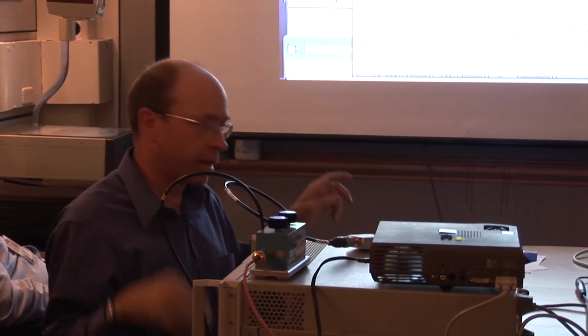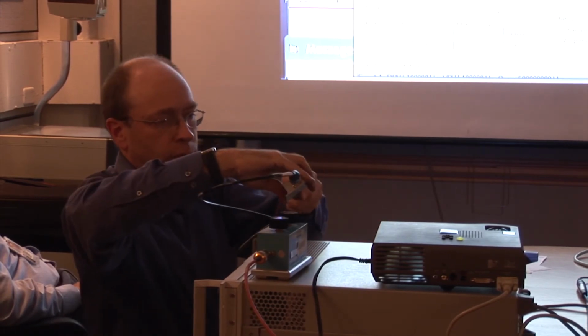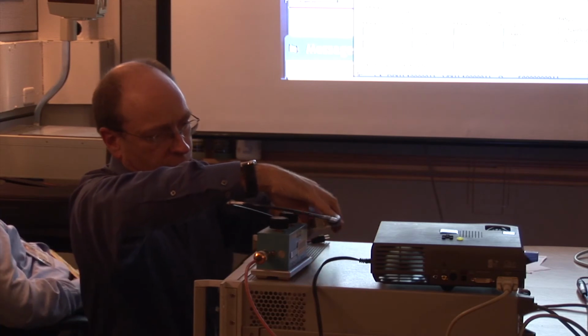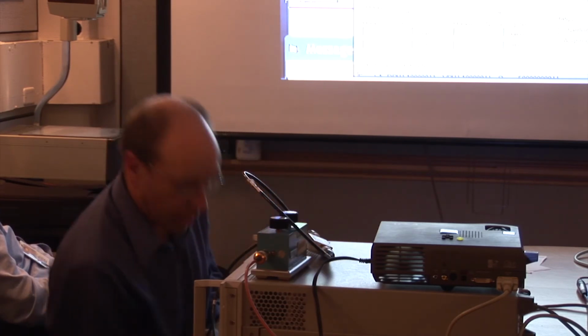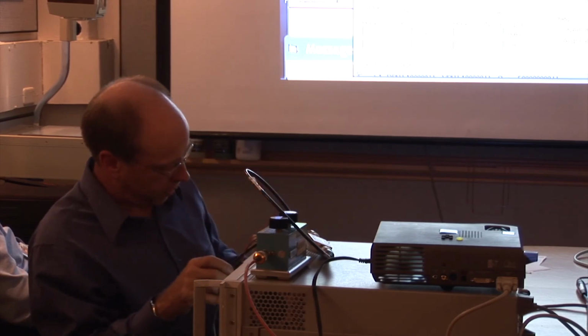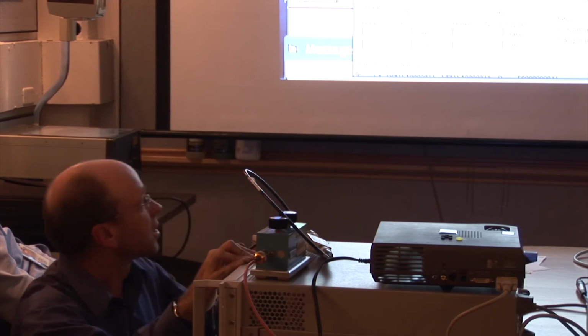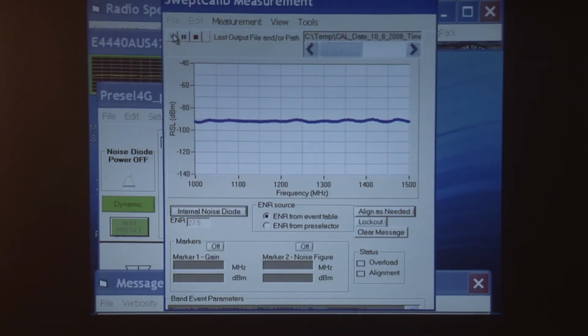Okay, turn on the preamplifier, 15 volts, like so. Okay, now, sorry for the delay there momentarily, but we've now put in an auxiliary preamp, electrically speaking, at the bottom of that long RF line at the input of the spectrum analyzer, remembering that our noise figure here was running about 5 or 6 dB, and gain was about 3 or 4 dB. Let's go ahead and rerun the calibration, please, Randy. Diode on. Collect the data points. Diode off. Collect the data points.